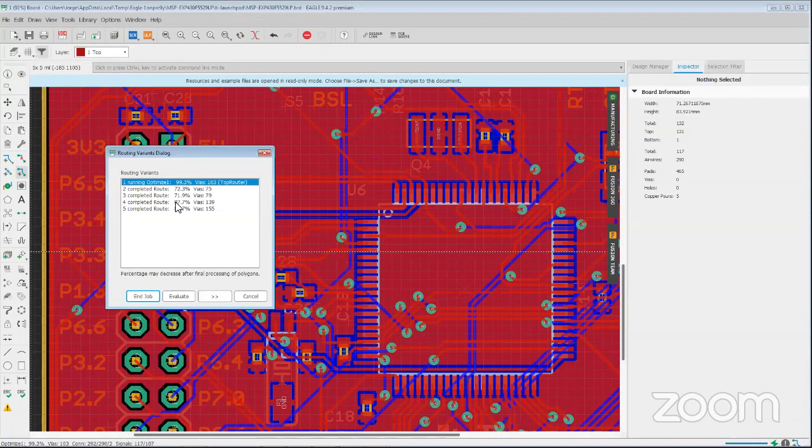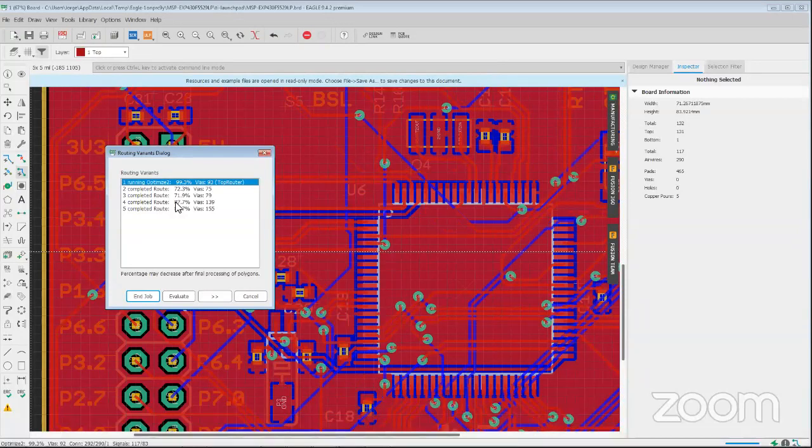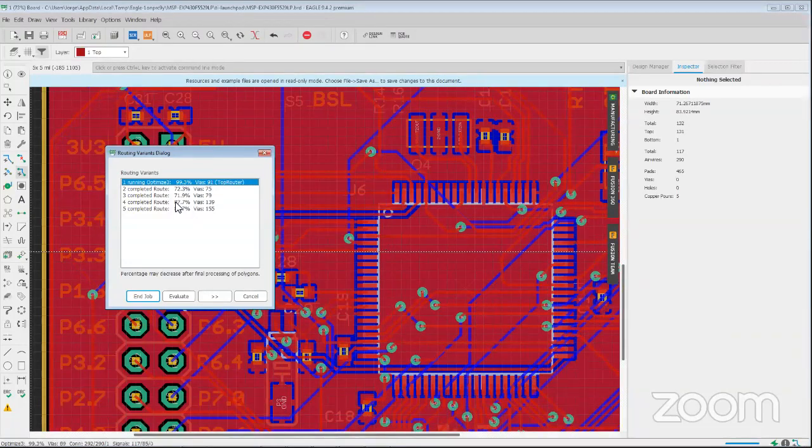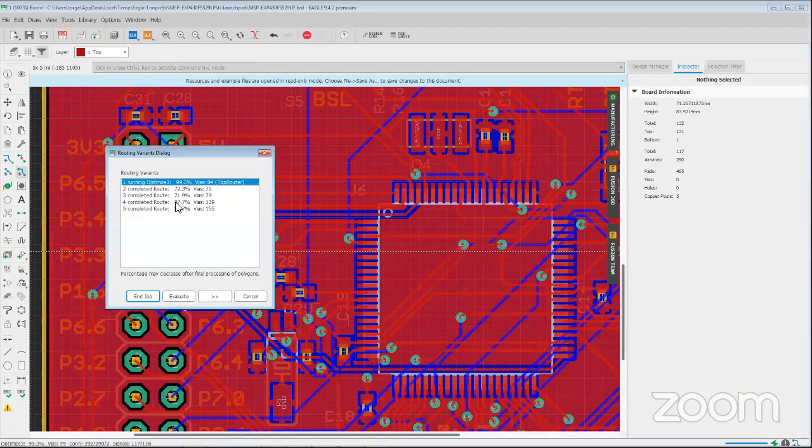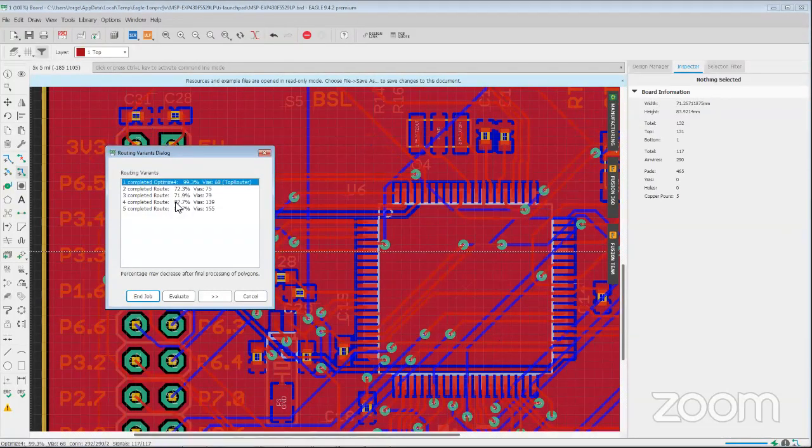There'll be instances where you don't want the topological router because you see it going straight through buses or something like that. So it's common to just turn it off, because remember, when you want to use the auto router, you could either have it do the entire board or you could just select what signals you want to route. And there will be instances where you want to use the auto router multiple times, so you will only select certain signals. Let's say you want something that's just straight through and you don't want to use a quick route. You could select those and turn off the topological router because it's just a quick run, and the space you have may just be single sided. So you don't have to worry about it. That way you just get faster results.